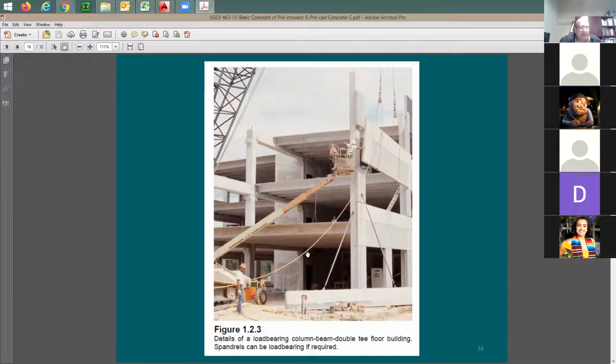So someone's going to say, how about structural steel? Why don't we do it out of structural steel? Because structural steel is going to be very noisy, and the deck performance is not going to be as good as this. In structural steel, you're going to have steel columns, steel beams, and then a metal deck, and then a concrete topping. The problems that you're going to be facing in structural steel parking construction are going to be a lot compared to that.